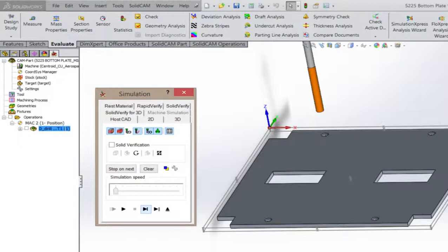I'm going to step again, and now I am at Z -1154. That's the 78 thousandths of the material plus the tip of the drill bit plus the delta that I put in there. And then I step again, comes out to 5, step again.